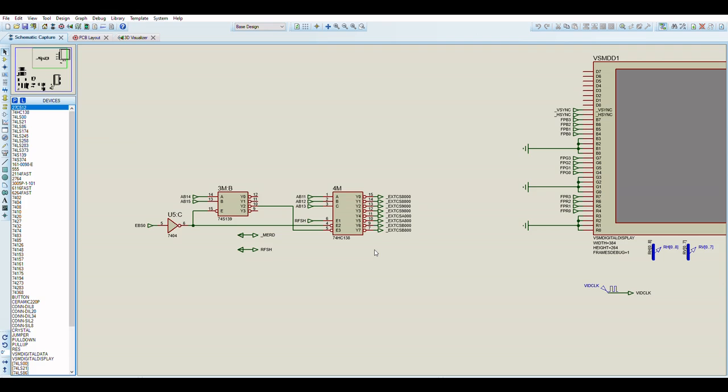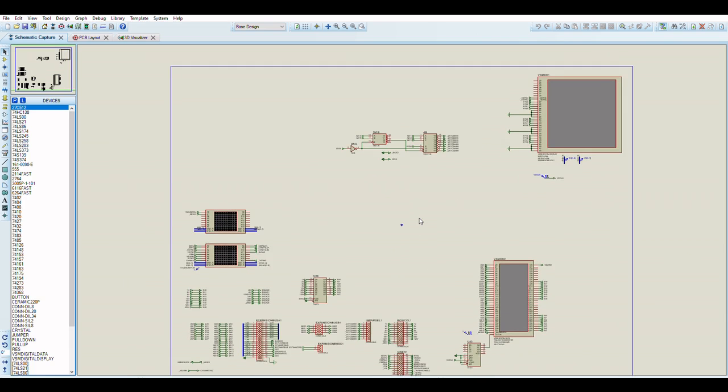Whereas on the original Bomb Jack, with the exclusion of the mode 7 screen, which wasn't in the Bomb Jack hardware, all of these were originally ROMs, and as I said, I wanted to make them RAM. So I mapped those to different extended bits in the extended memory bus register, if you like. Effectively, it means that we have the 16-bit addresses that would have come from the CPU, plus 8 more bits, to give us a whole bunch of extra memory. So basically up to 24 bits of extra mapped memory, if you like,